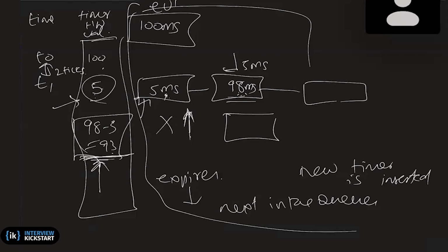First of all, we are not using a fixed tick like 1 millisecond. That is in the normal ticked mode of the timer. In the tickless case, you are programming the hardware for multiple ticks. It could be 5, it could be 100, whatever it is. So there is a slight confusion there. It is not like every 1 millisecond there will be a tick. There is no fixed tick. The tick is variable. That is why it is a dynamic tick. It may happen after 5 milliseconds, it may happen after 100 milliseconds. We don't know.